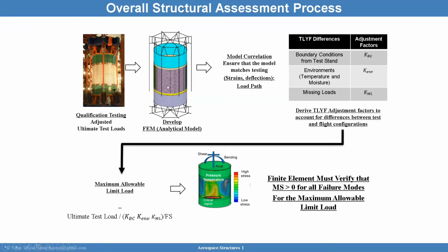Am I getting the right load paths in the structure finite element model? Another thing that's important here is that you want to make sure that the test is actually doing the right thing. So are the actuator loads applied into the structure correctly? That's what the finite element model could show you.